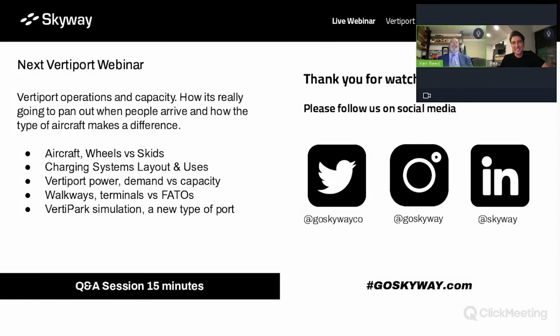Okay. Yeah, certainly. Some vertiports may operate very efficiently and not require as much parking as others because passengers will always be ready to go, for example. But we do know that different vehicles are going to require different charging times. So that will change the number of parking spots that you need. It's possible you might have a vertiport that has a critical aircraft that is larger than others. So you might have some parking spots that are dedicated to larger size aircraft and some that are smaller.